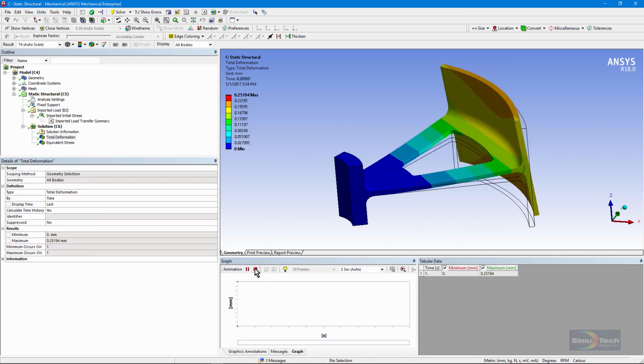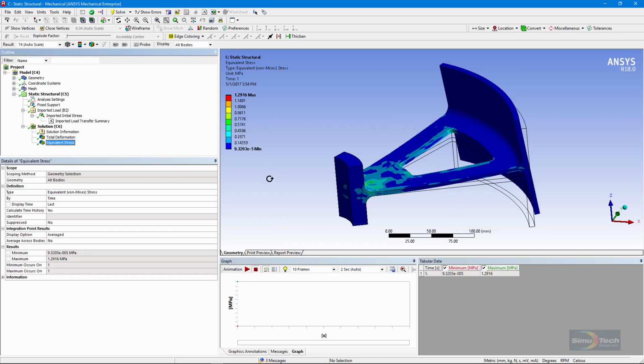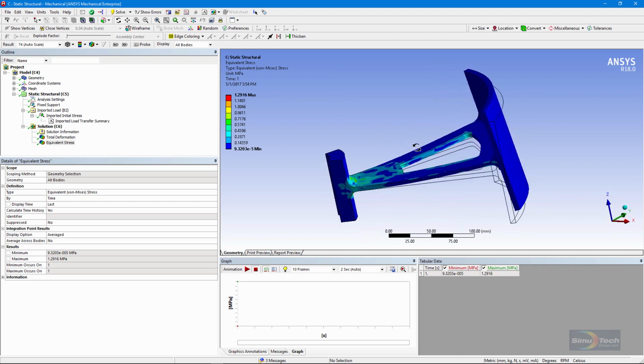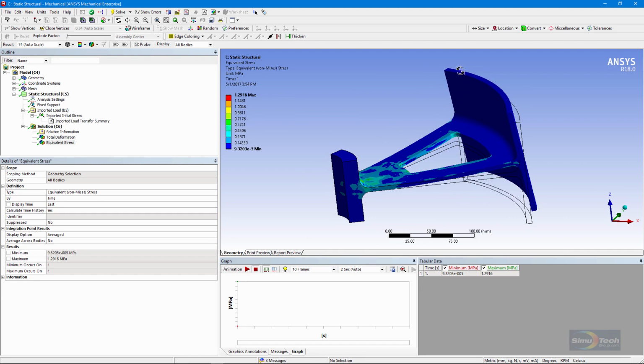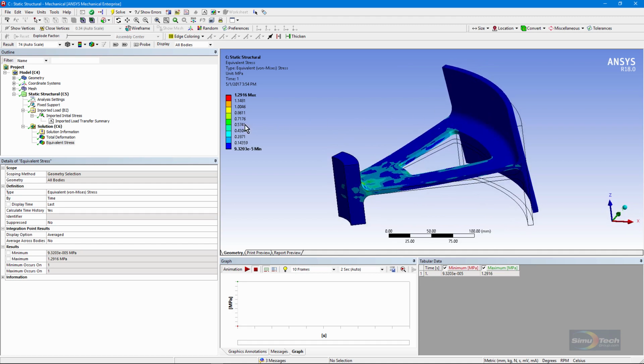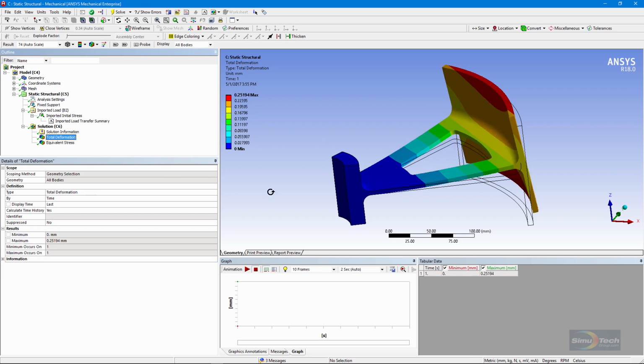And if we were to go look at the state of stresses, they're a lot closer to zero. They're not right at zero, but whereas they were up around 10 megapascals before, now they're down around 1.29 because we don't have any loads applied. Just that state of initial stresses. There's no load on the edge there, so you're not going to get exactly a zero state of stresses, but it does relieve itself quite a bit when it's unloaded, and the residual stresses produce the movement you see. There's the final deformed shape again.